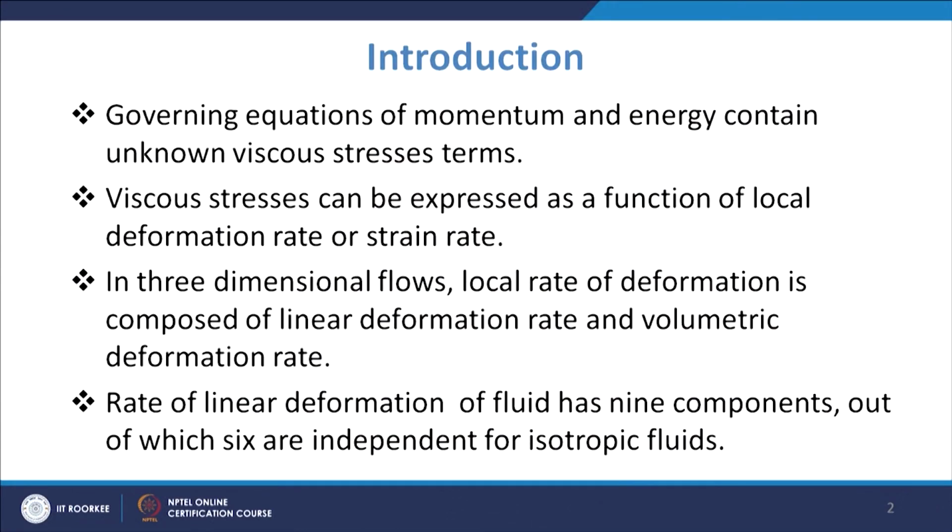So, the governing equations of momentum and energy contain unknown viscous stress terms, that is tau xx, tau xy, tau xz and so on. Now, these need to be expressed in a measurable manner, and they are basically expressed as a function of the local deformation rate or the strain rate.